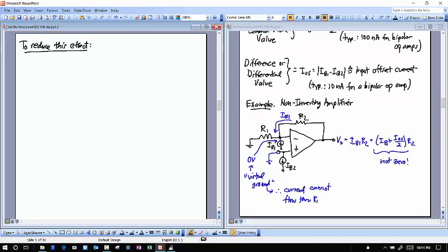So you can see right now at the positive input in this circuit to the right here, this current IB2 is just flowing straight through that ground there, and it's not creating any voltage across there. But if we can create a voltage here, then we might be able to take a current component here, which then absorbs the current IB1 and sort of cancels what voltage comes out to V0.